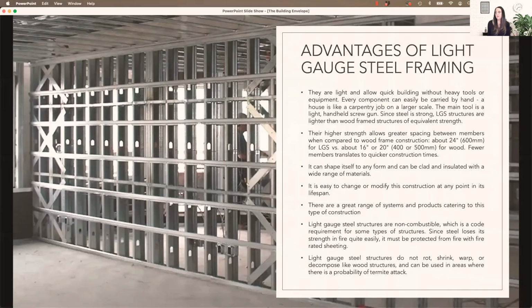And then for floors, there is the light steel framing for wall systems as well in commercial projects. And again, like I was saying, we're working on that project where we have the light gauge framing, and we've added those wood blocking pieces running horizontally between the studs so that we have places to adhere to when we're installing cabinets or other heavy images or heavy products.